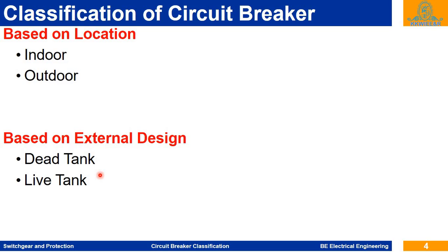This is the basic function of the circuit breaker, but where these arc interrupters are placed, based on the construction of the circuit breaker, they are classified as dead tank circuit breaker and live tank circuit breaker. So based on the external design, they are classified as dead tank and live tank circuit breakers.